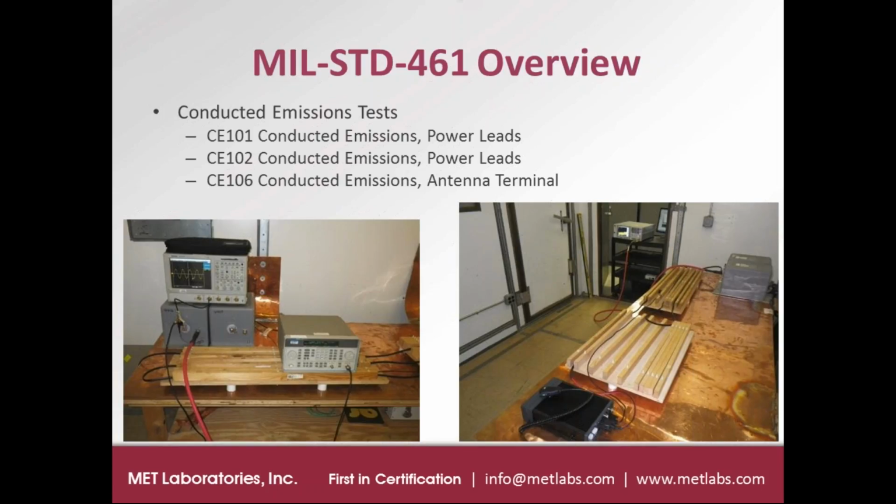So there's 3 conducted emissions tests in MIL Standard 461, and they cover a range of frequencies as well as types of emissions that are conducted out of the EUT as an unintentional byproduct of its normal operation. So CE101 covers lower frequencies for conducted emissions current measurements, and those measurements are taken with a current probe around each input power conductor in the frequency range of about 30 hertz up to approximately somewhere between 10 and 100 kilohertz.